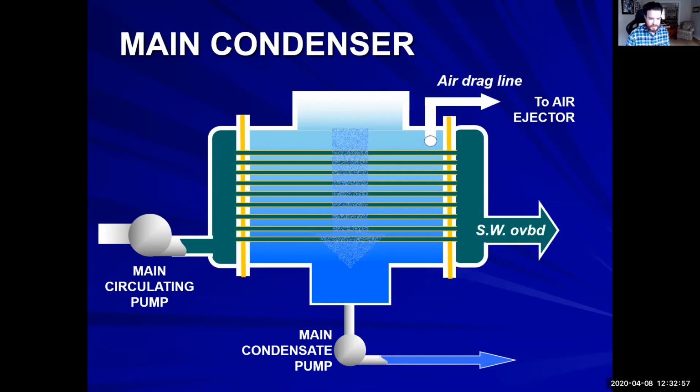So on board the TSES, we also have something called a scoop. And it literally is on the bottom of our vessel. And it sticks out on the bottom. And basically it just scoops up salt water from our movement and goes into our condenser. And then it spits it overboard.